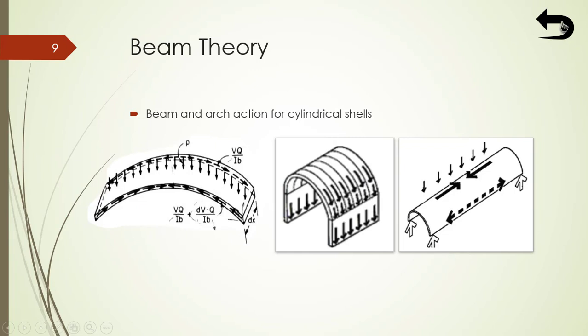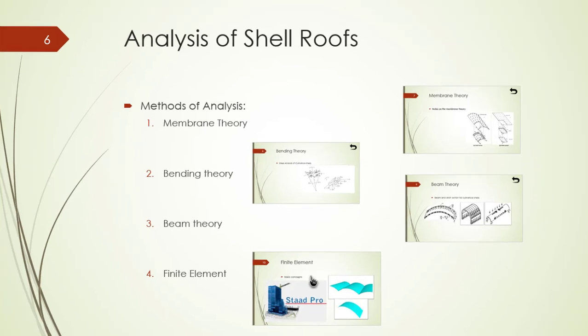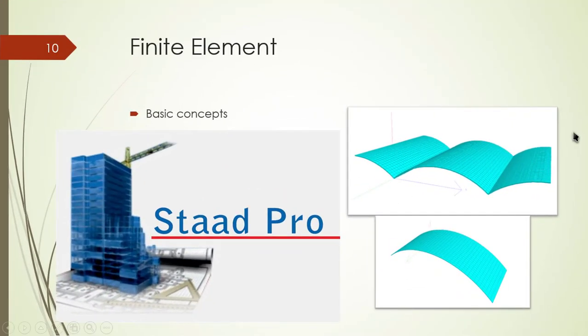And we can see in this figure the predominant longitudinal forces along the shell and the arch behavior of the curved cross-section. The finite element method is a numerical technique for solving problems which are described by partial differential equations or can be formulated as functional minimization. A domain of interest is represented as an assembly of finite elements.